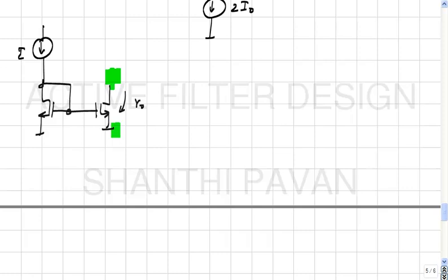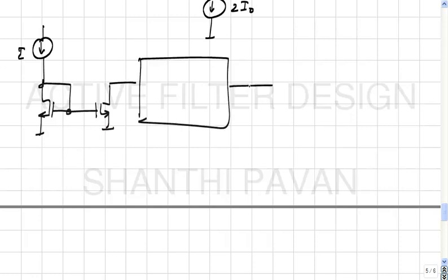So if you want to take a non-ideal current source, in other words, a current source whose incremental output impedance is not infinite, and make it look like a better current source. In other words, what is a better current source? Higher output impedance. Then what would I put between, if there was a black box here? What kind of control source would I put?